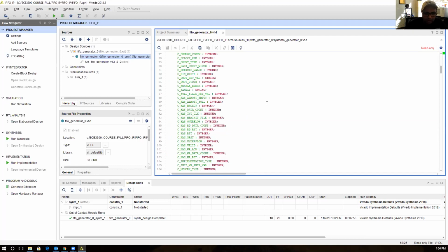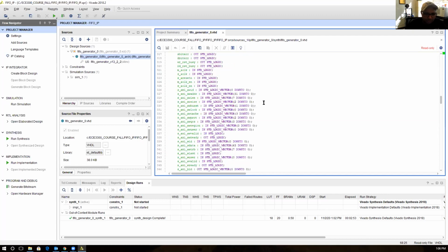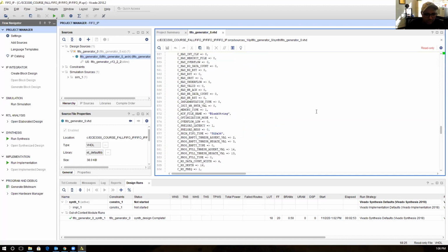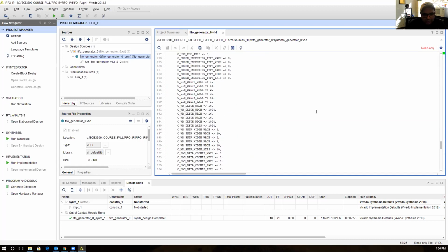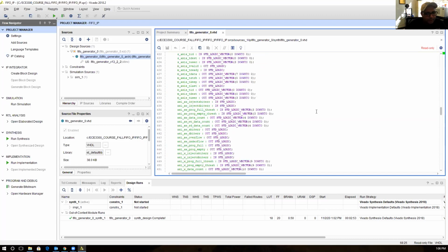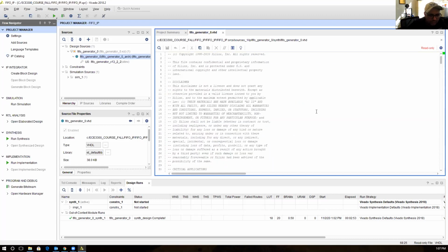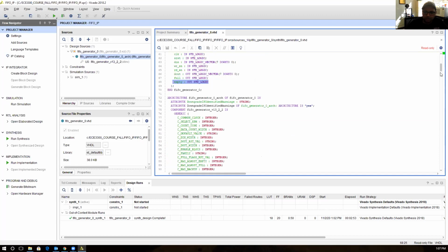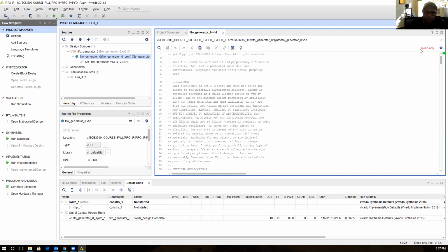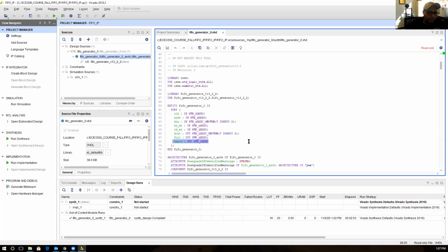You can call it and make a test bench, and you can see how it works. So internally, it did all of this AXI stuff that, with AXI buses, you don't need, and you just activate stuff, deactivate stuff. You don't need all of these things. It is HDL generated. That's why it's called read only. You can convert it to a writable one, but they will not allow you. You just need to take this one.